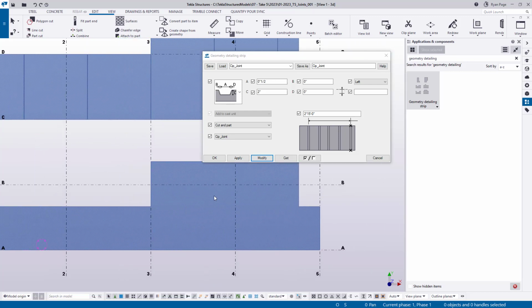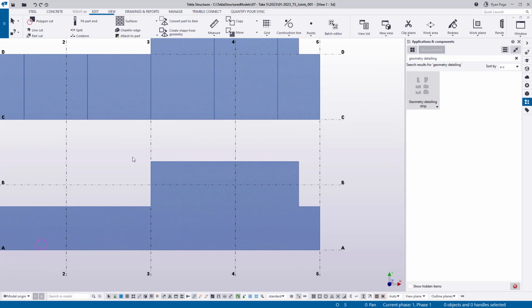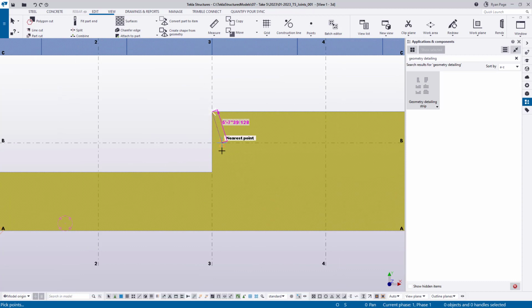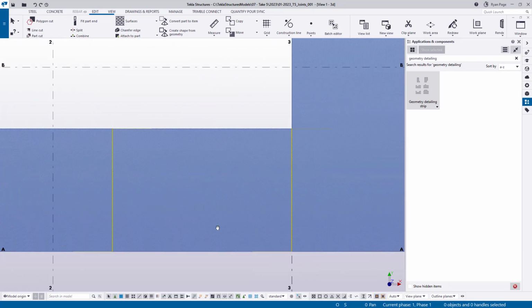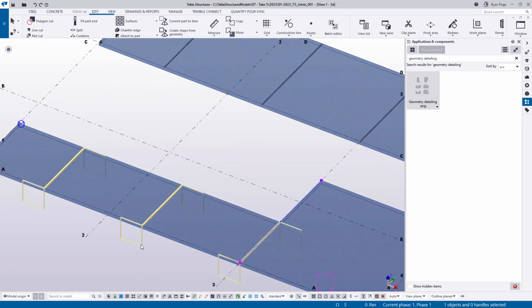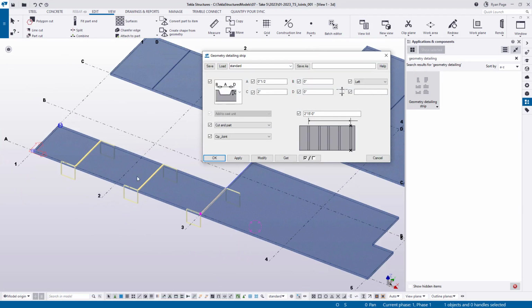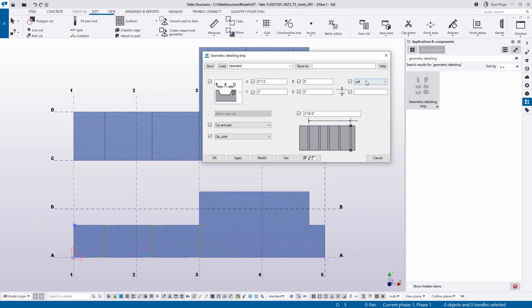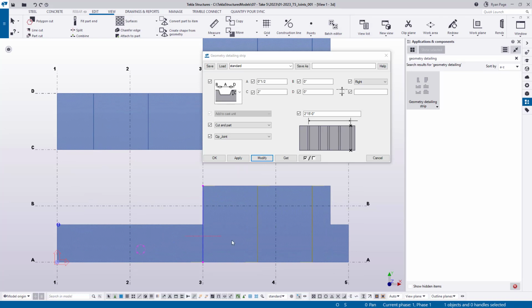So if we delete this, apply our settings, come back over, and activate our tool, select our face again, and then go from start to end point there, middle mouse click. Now what we have, as you can see, is it's populated these for us based off of the tool's applied settings. We bring that back up, it's going 2 and 15. So notice that it's always placing the joints to the left. You can also do it to the right and hit modify, and it should switch sides. See, there we are. But notice now it's adapting to the thickness.